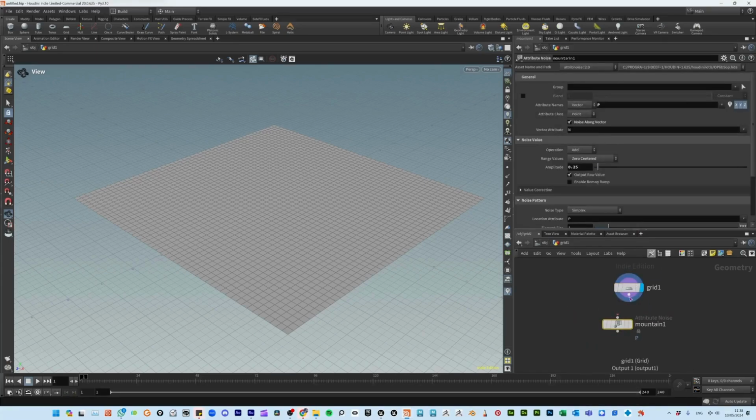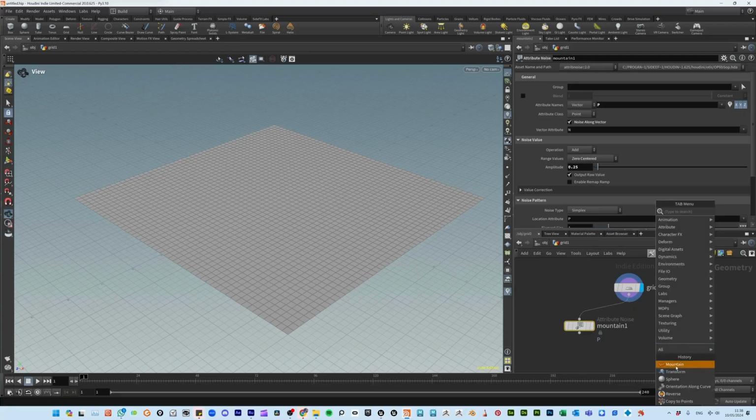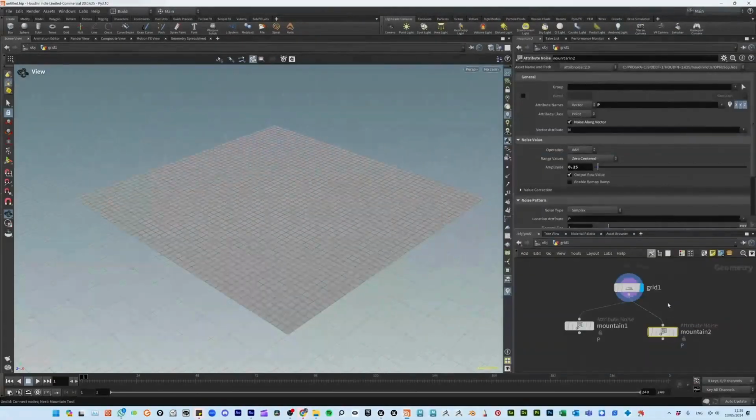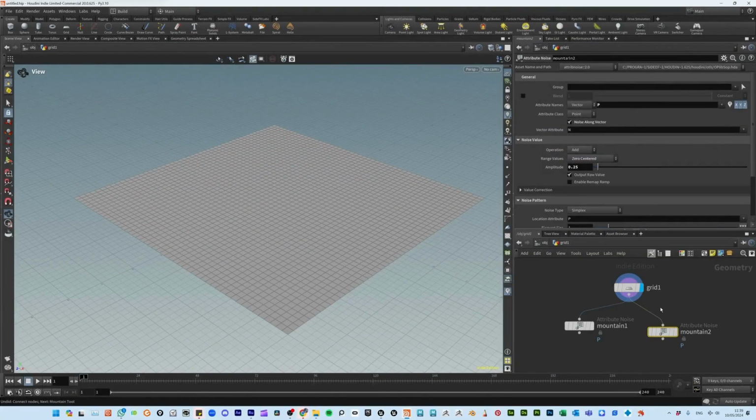Then I need to make a connection. I can either take from the output to the input or the other way, but I need to make a connection. The other way, I can build a node, right-click. I have a history here of the nodes I used. I can press J and draw a line somewhere in the vicinity of both the input and the output. I can easily cut the connection either by pressing Y and having the scissors on it, or pressing the connection and delete. So again, either connecting or pressing J and drawing a line to have the connection.